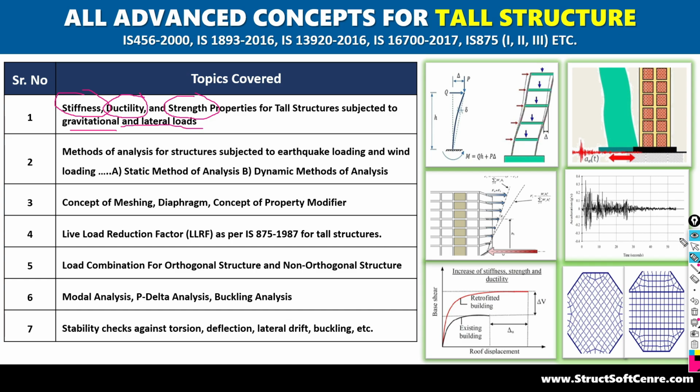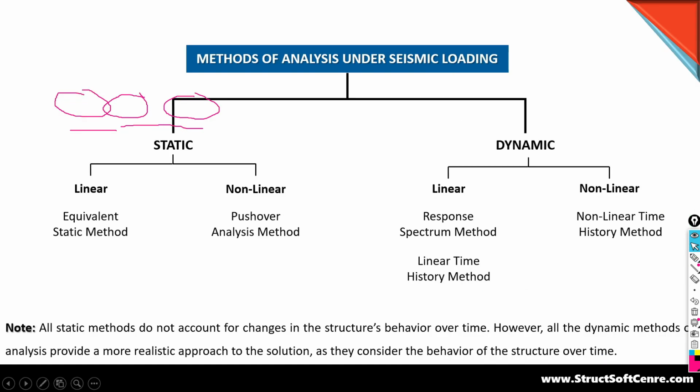Then methods of analysis. What are the different methods of analysis available? Static analysis and dynamic analysis. In static analysis, the equivalent static method is there, and non-linear pushover analysis is there.